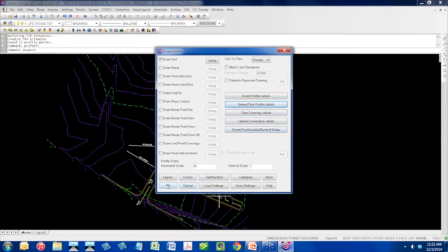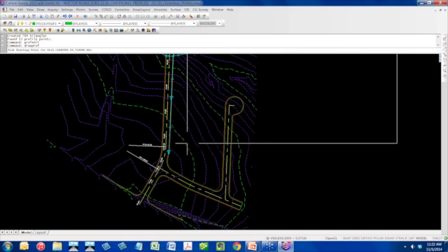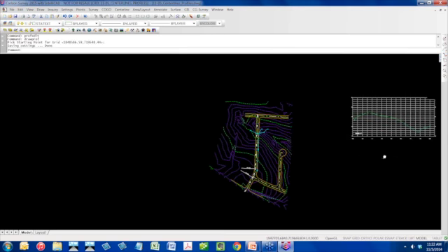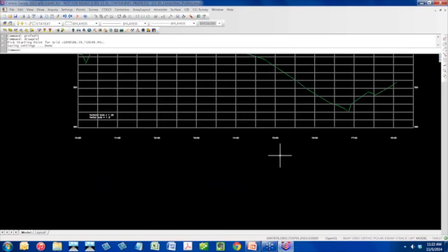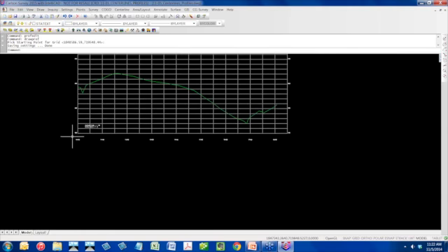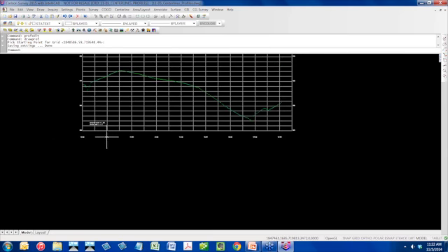For now, let's just basically draw this generic existing ground profile. I'm going to set the bottom of my grid at 580. Make sure I've got some room down there. It gives me a preview of how big that grid is, so I'm just going to place it here. And 580 was kind of low. All right, and for some reason, yeah, I need my settings. I'm not even getting my elevations here.